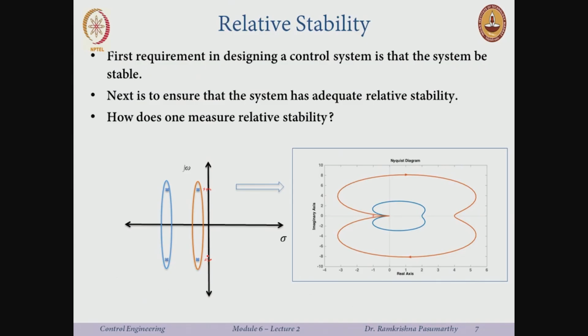Okay, so how does the Nyquist plot look now? Here I cannot directly measure relative stability. I can say, well, this is further from the origin, so it will still be safe if there are some changes in parameters or things like that. It may come slightly to the right, or maybe even move to the left, and so on. But I can say that the blue line looks a little more hopeful than the brownish one, right? This is for the paired poles.